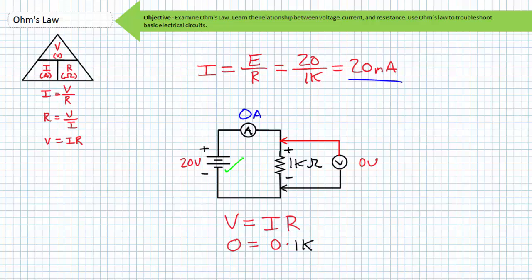What if the source really was on and you still observe no voltage drop? In this case, again, there is no current through it. What is stopping the current? Perhaps something with an infinite resistance. I previously assured you that it was in fact a 1 kilo ohm resistor. However, is this really the only element in a circuit with your source? Or is there something else in series with it? Think about what I'm asking. What is something with an infinite resistance? Something with an infinite resistance is an open or an incomplete circuit.